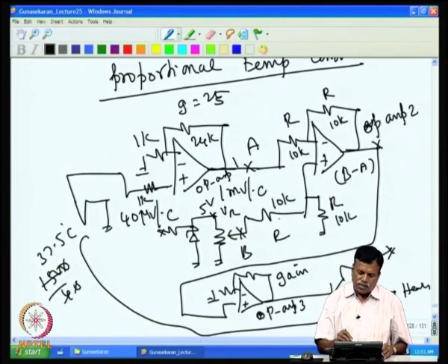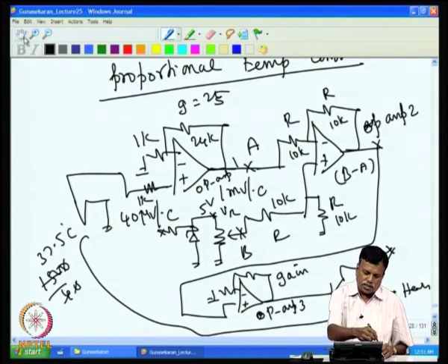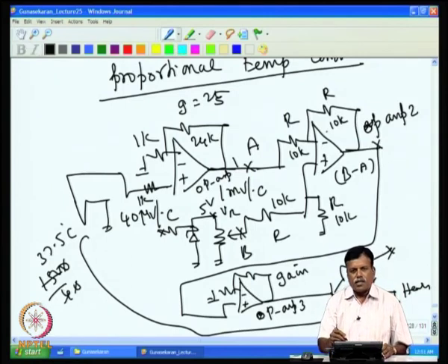One thing: if these resistances are not matched, which we discussed earlier when we were discussing constant current sources, say they are 10Ks, but they may have 1% error if I use 1% resistors, and they may have a 10% error if I use 10% tolerance resistors, then that will act as a common mode error.